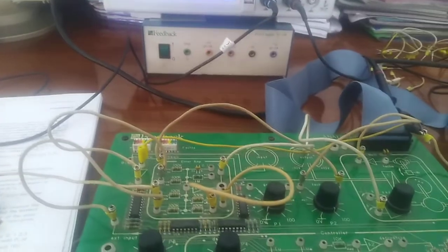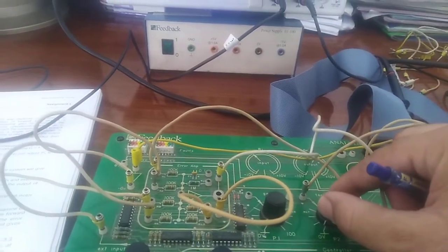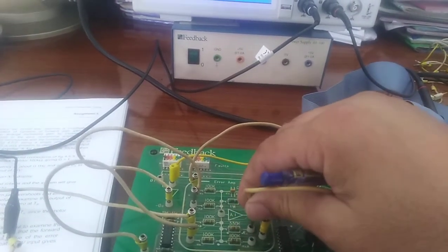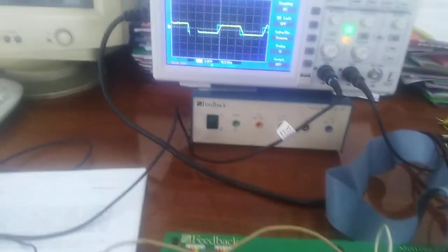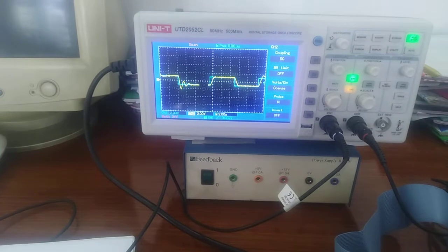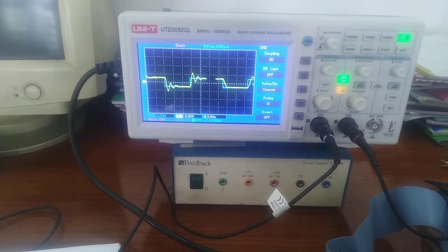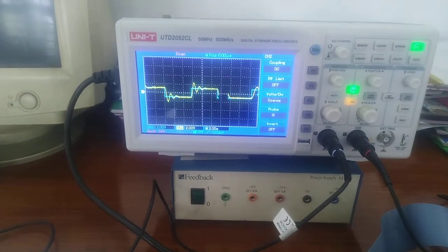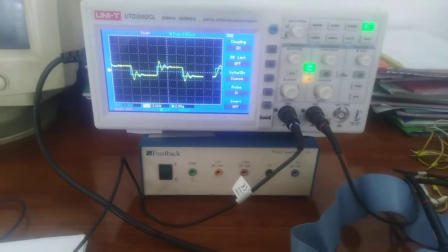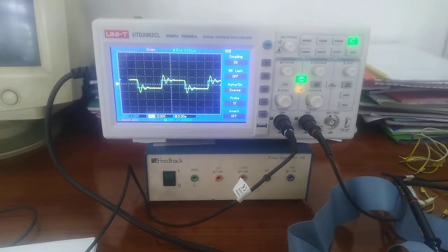Let me decrease the velocity feedback again to 0, and I'm increasing the gain. For example, if there is some steady state error in the system, that steady state error can be eliminated. So by increasing the gain to 3.3, transients are induced in the system, you can see here, and these transients can be further improved by velocity feedback, where by means of the velocity feedback these transients are differentiated.